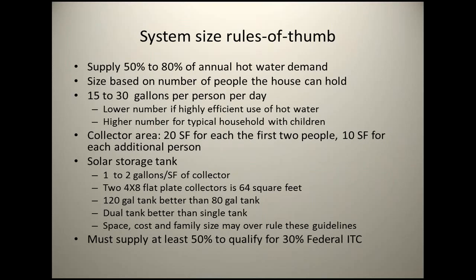Okay, so how do you size these systems? The design goal is between 50 and 80% of the annual hot water usage. So we're not trying for 100%. We're trying for between 50 and 80. 70 is doing pretty good.